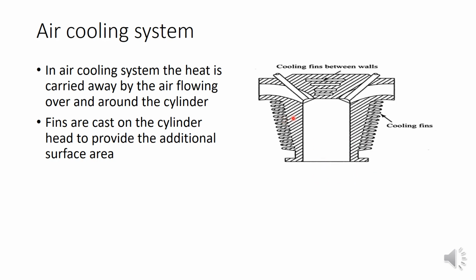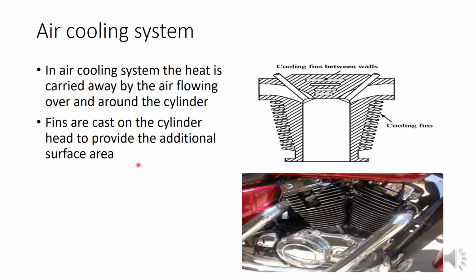And to increase the heat transfer by convection, we have to increase the surface area. And by attaching this fin, we are simply increasing the surface area of this system. So this is the fin in actual figure. You can see a number of fins are there outside of the engine cylinder, made of aluminum almost or some other high thermal conductivity material.